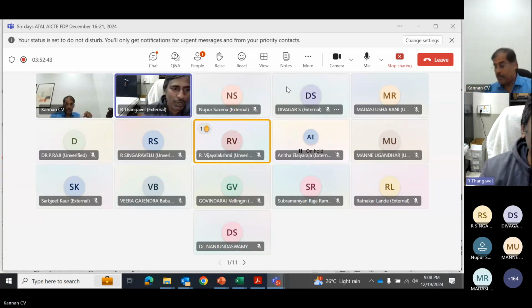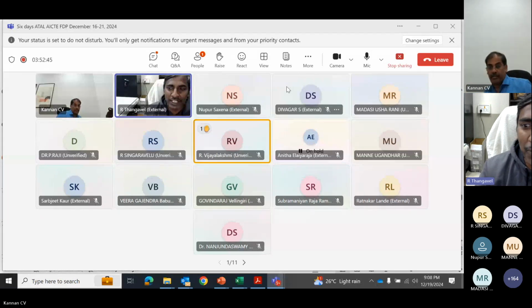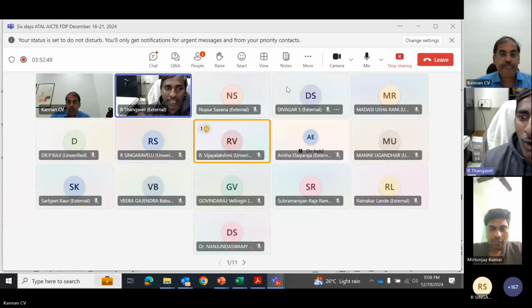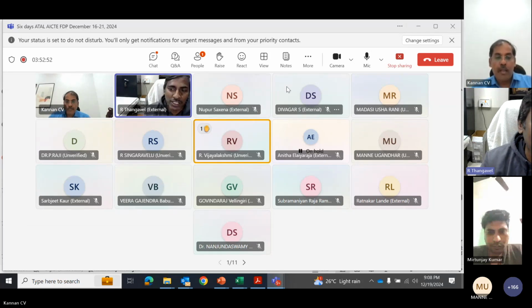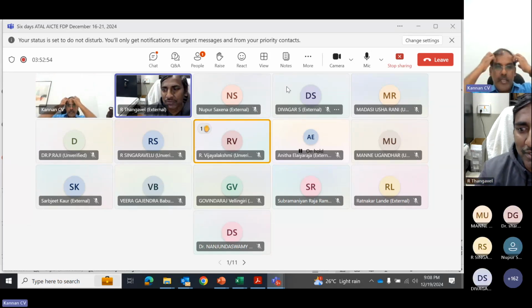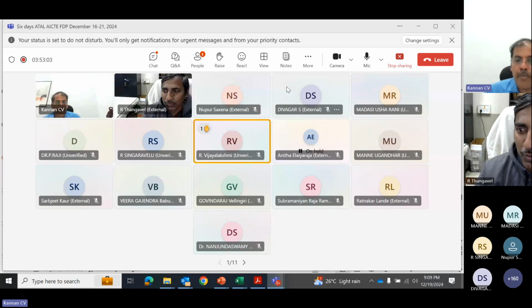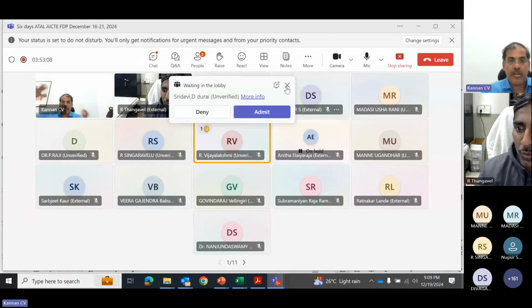Sir, one participant is asking: you said N-type solar cells started in 1954, then the industry moved back to N-type back contact. What is the reason they are starting again? Okay, as I said, it started with N-type, but the production of an N-type mono ingot is not that easy because it has a wide resistivity range, and the growth process is a little bit difficult.